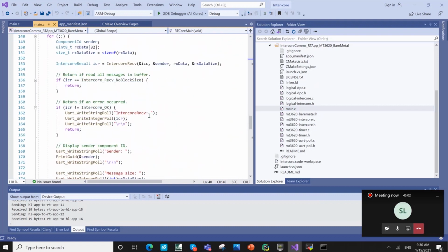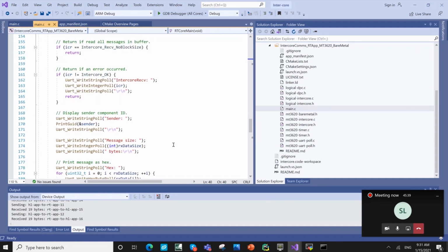So one of the applications where I was working, where I needed real-time communication with a LoRaWAN sensor, I used the real-time core to communicate and talk to the LoRaWAN module, and whatever data I needed to send across to a LoRa network, I would use the real-time core, and whatever message I needed to get from my Azure portal down into the high-level core, and then push it down across. So that is one of the applications I have done using this.